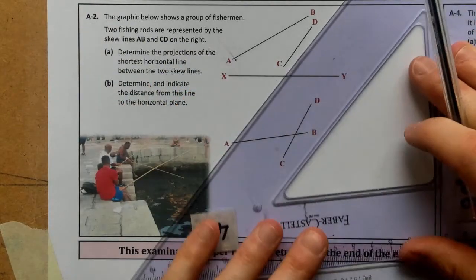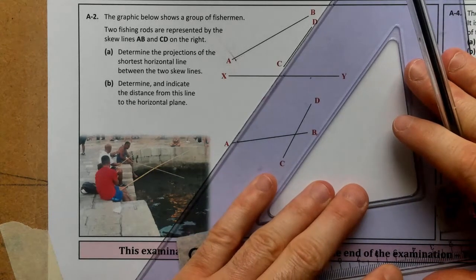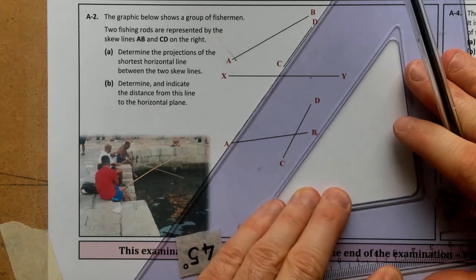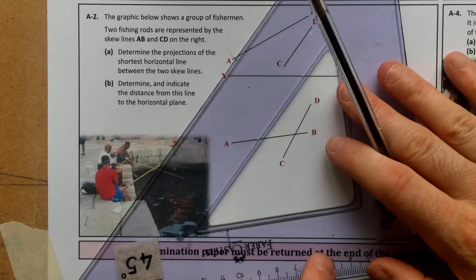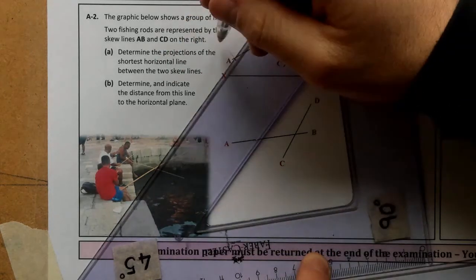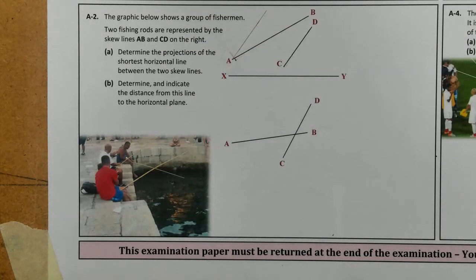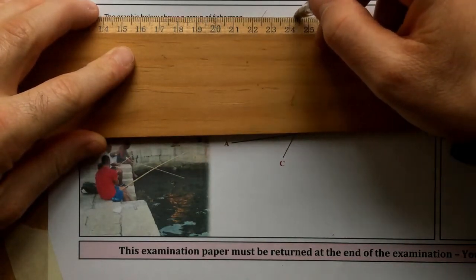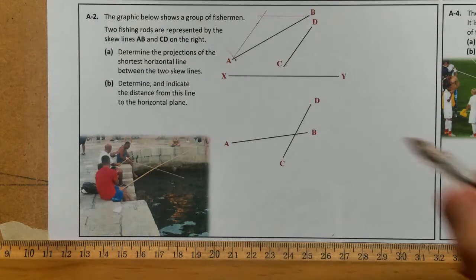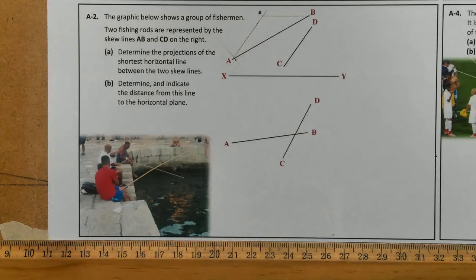So I'm going to go parallel to CD in my elevation, from A, and where that is extended up, I'm going to project across horizontally from B. Essentially what I'm actually finding there is another point. I've created a plane surface. I'm going to just call it E. I'm going to call that point E right there.